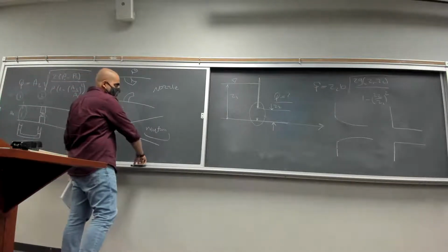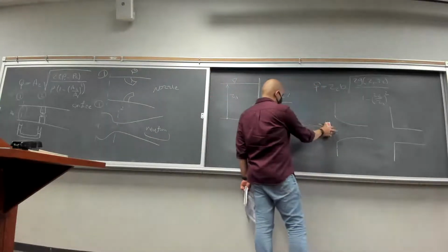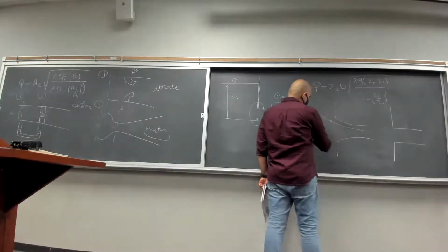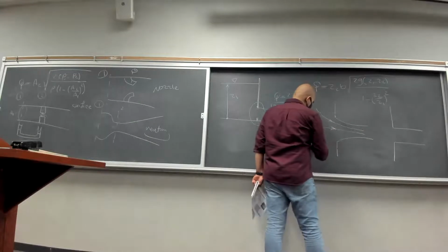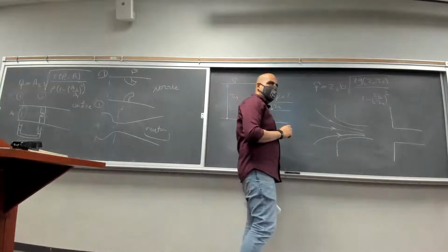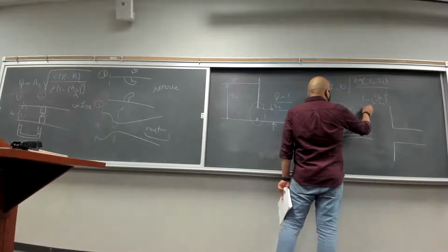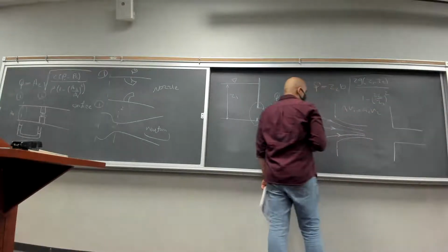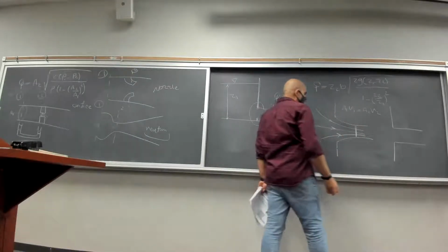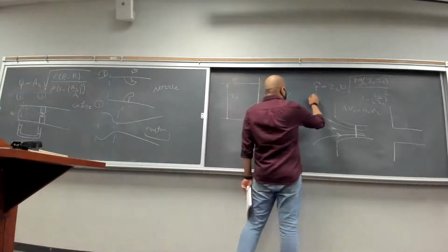But why is that? Essentially, the reasoning is very simple. Right? Here, when you have the streamlines going in, the transition is going to be very smooth, right? So the flow is always attached to the walls. And when you write this continuity equation, right, this was the continuity equation, the area you are using has to be the flow area, right? Which is essentially the same as the pipe area in a well-rounded entrance.